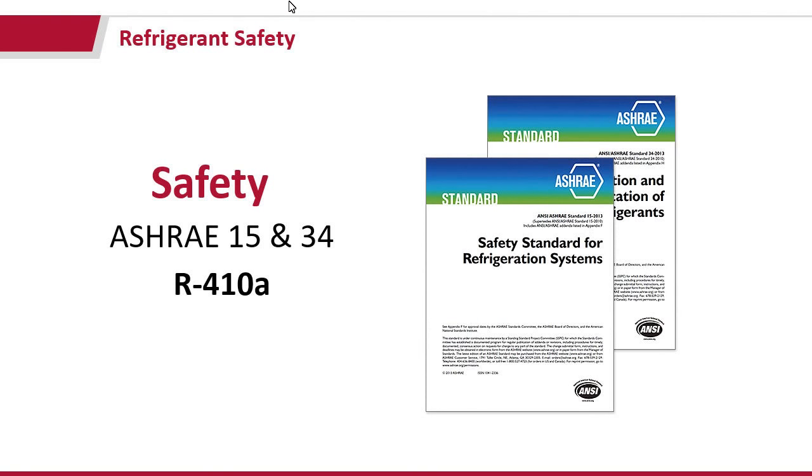Also, another thing to keep in mind is obviously refrigerant safety. I'm pretty sure we've all seen these codes at some point or another. ASHRAE 34, which is just general ratings of refrigerant and the safety standards. And then ASHRAE 15 is the one about if you have a refrigerant leak and it all was hypothetically to leak into your smallest zone, then it has to be under a certain amount in order to maintain the safety standard.